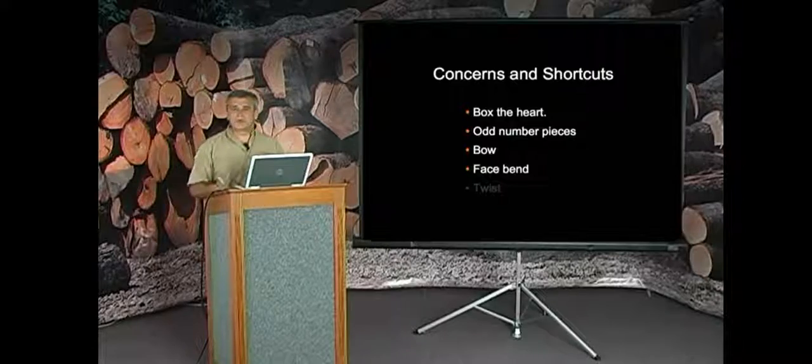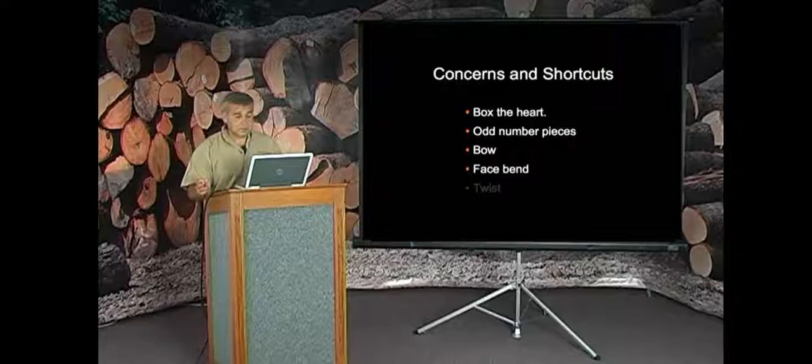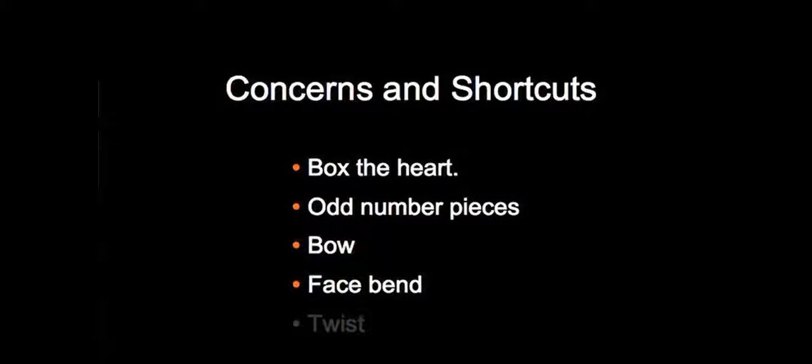Try to do that with bow. Why, you're wedging and cranking and trying to push the middle, so you're fighting every board. It's a terrible defect to have in a sheeting application, whether it's your subfloor or your siding. Bow is a nightmare to deal with. Face bend's a little better.